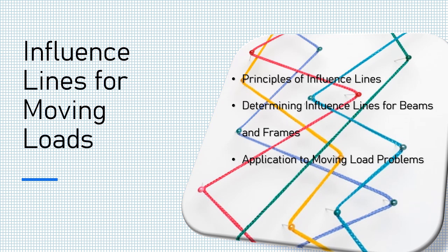Once you have calculated the internal forces for different positions of the unit load, plot the results on a graph. The x-axis represents the position of the moving load along the structure, and the y-axis represents the value of the internal force at the point of interest. 8.4. Examples of influence lines for common structural components.